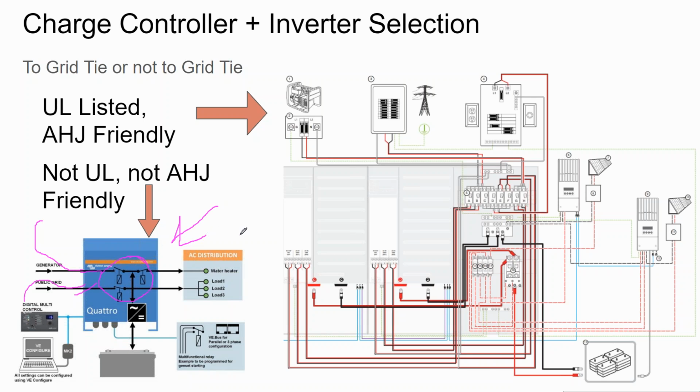Other kinds of battery inverters are what's called stackable. And so here's inverter 1 and here's battery inverter 2. And what you can see from this line diagram is the outputs of the inverter, I think this is the output here, is landing in parallel on an AC bus bar, and the generator is also being wired in parallel.